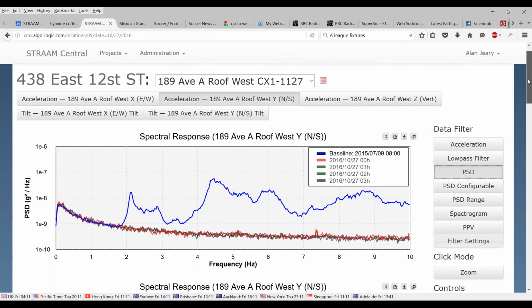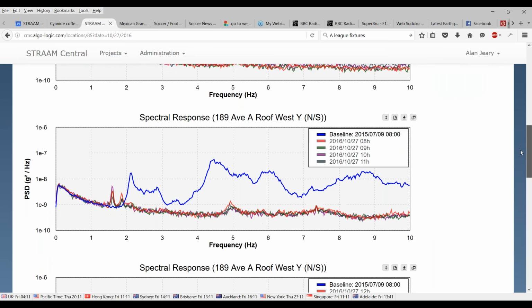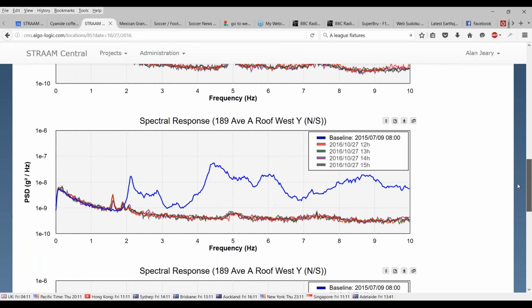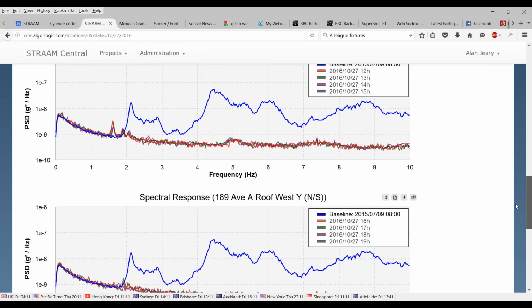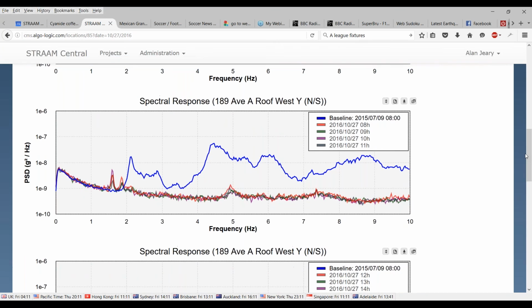There is an area where construction has occurred, and this particular building was not in a very good state, but the placing of a new building has added stiffness to it. It's also added mass, so the frequency has decreased, but effectively it's made it more stable. So we expect the frequency to go down there. And you can see the whole response is much cleaner, much better.